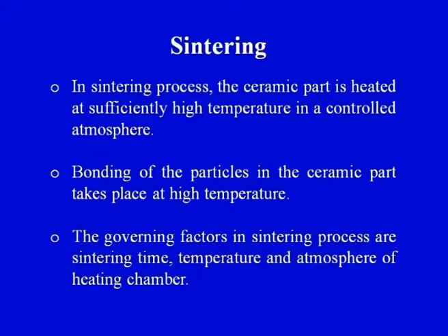That we are going to see in the next slide, but first we need to understand 2 or 3 important points, that sintering is a process that is done at elevated temperature under controlled atmosphere. This is point number 1. Point number 2, the bonding between the individual ceramic particles takes place when sintering is done. Now, what are the governing factors in sintering process?